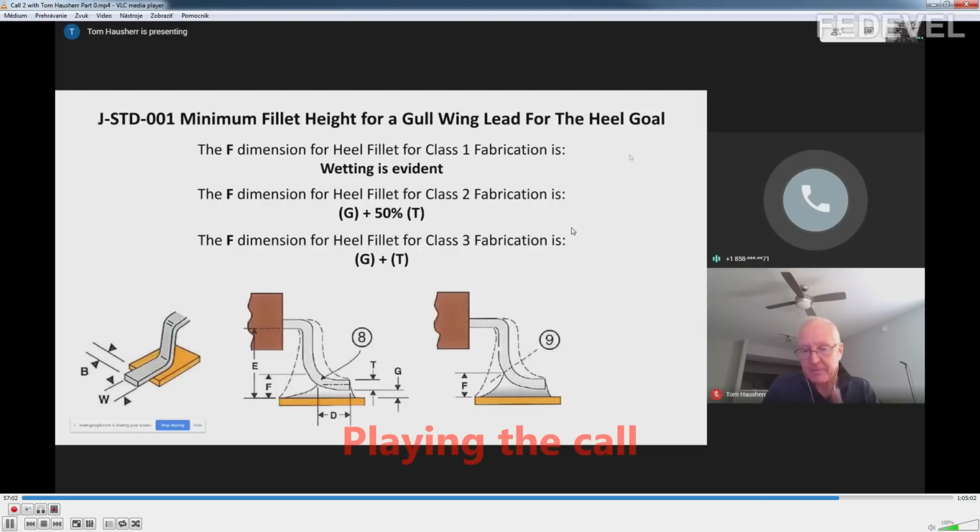If you have a trace in a space and you have a solder mask and everything else, you don't want to violate that electrical clearance. So if your lead hangs off the pad, it's okay as long as it doesn't violate the minimum electrical clearance. Therefore, in the world of land patterns, for toes, there doesn't really need to be one, because it doesn't make any difference to J-STD-001. They don't have any information on any tables.